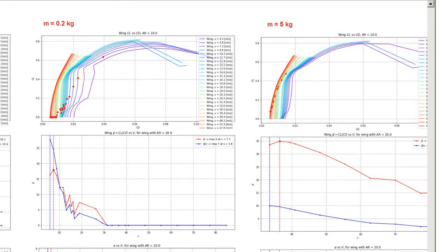And also for the small mass, you can fly at small speed, but you would have to go to the low Reynolds number, and low Reynolds number is a big issue, because the solution does not converge and so on. So you don't want to go to the low Reynolds number, probably not to 4 meters per second. If you fly there, you have computational problems.